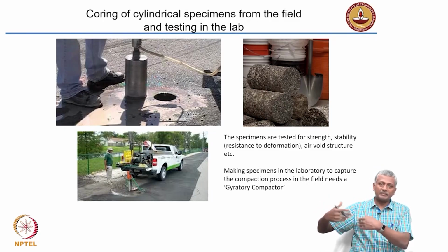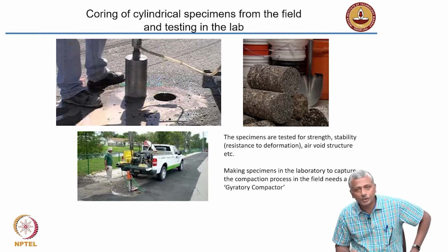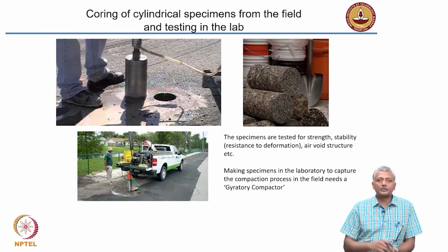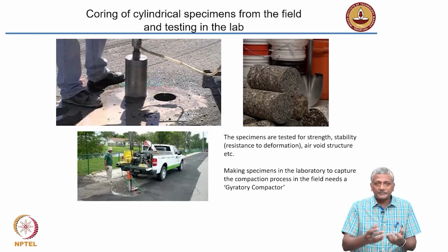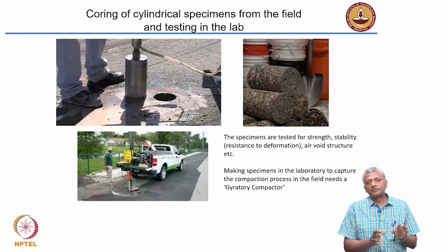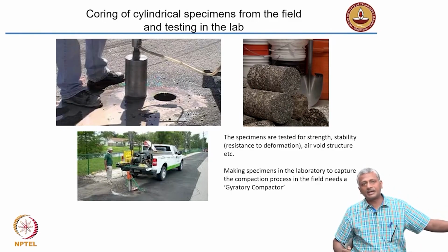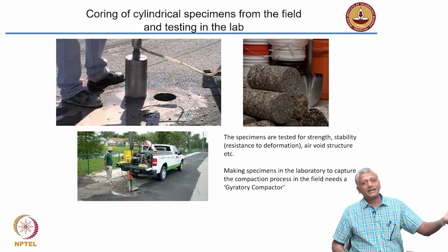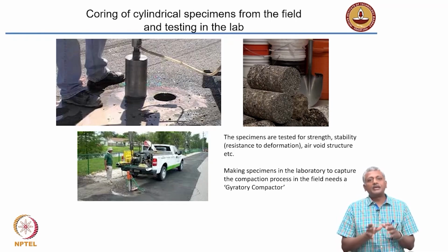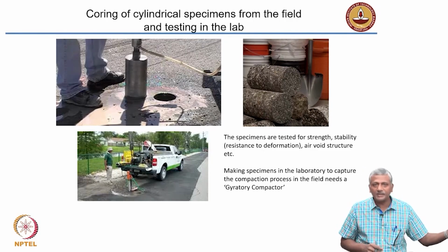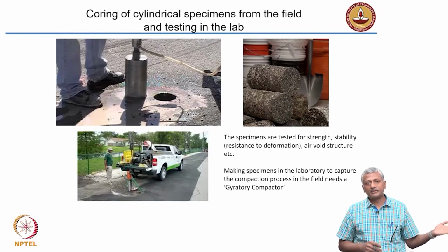You can use different methods of compaction. I am not going to cover that here, that is going to be part of a higher semester course for you in highway materials. But what I am trying to say is, the compaction energy of the real life pavement construction example can never be properly simulated in the laboratory. So, because of that, sometimes we have to actually take samples from the pavement itself and do tests on that.